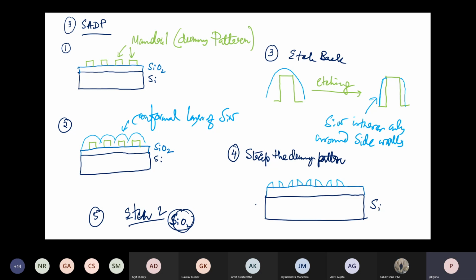In fact, when Intel first published their FinFET structure around 2010, 2011, people found that their pattern has different pitches. Then people started arguing that it might be due to overlay error, or it might be that they were using SADP. Okay, SADP pattern, right?